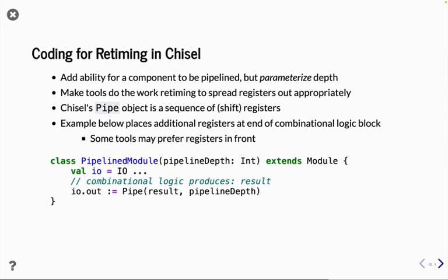Maybe you want to target a higher clock rate. You change your pipeline depth to 5. Once again, let the CAD tools move these registers around, right? So this is, like I said, the ideal case, and for ASIC tools, it usually works pretty well. Unfortunately for FPGA tools, not quite as reliable, but that's where we are.